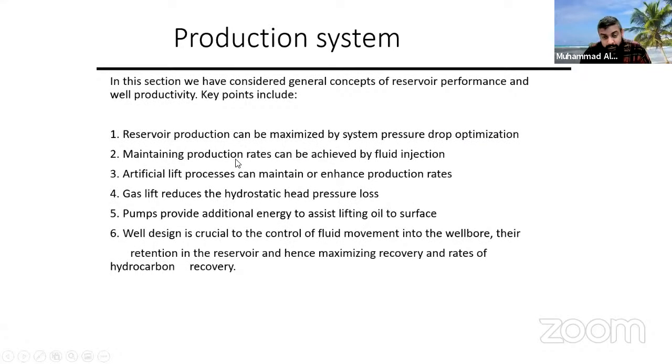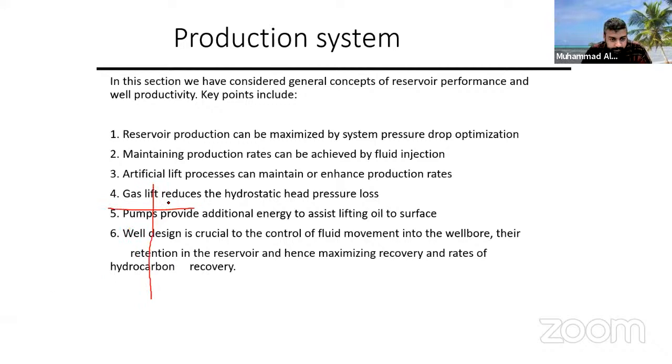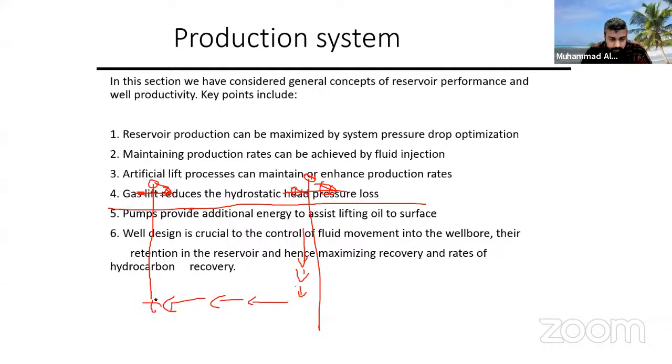The other thing which the reservoir engineers do is inject fluids. We call it EOR, enhanced oil recovery. Maybe you are injecting water, maybe you are injecting gas. So for example, you might have one well here. This is the production well, and this is the surface of the earth. You might have another well here. The purpose here maybe is to inject something, and that will go and push this oil, increase its pressure so that the oil can go ahead.